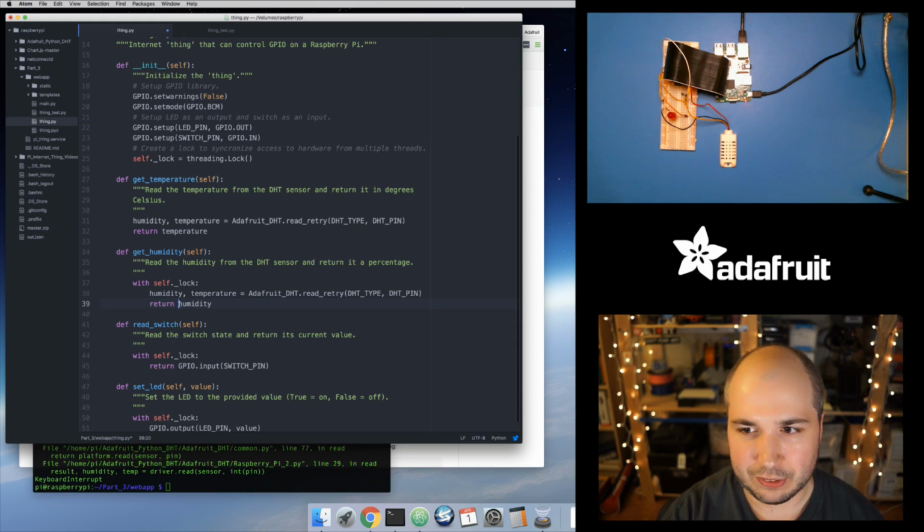It could save that sensor reading just inside of this class as some internal state. And then my get temperature and get humidity functions could just return back the last read result. So I'll have this little background thread that's just talking to my hardware, getting new data. It knows all about the sensor, and it knows I should only read it every 2 seconds to get the most recent results. So it can take care of all that. And then it simplifies my functions here in that they just need to return back the last read value. So let's jump in and add that logic here.